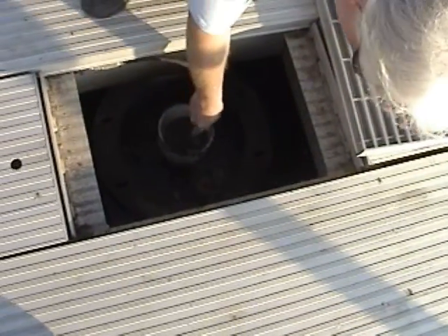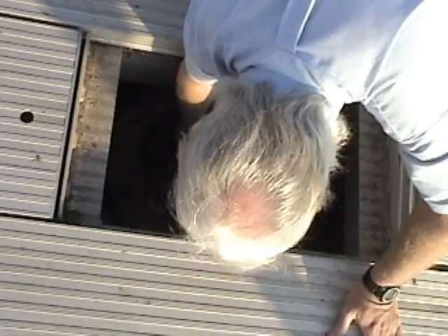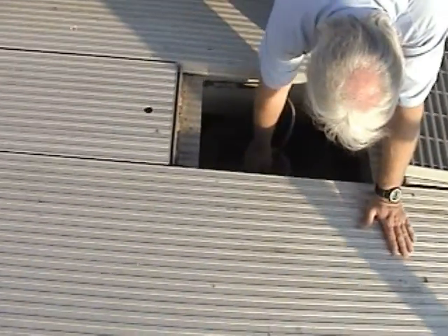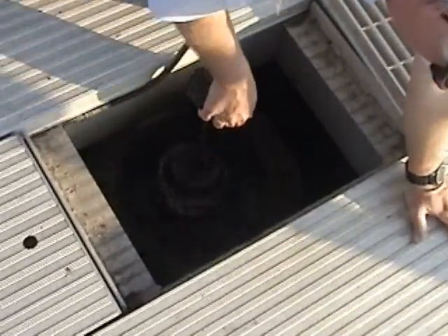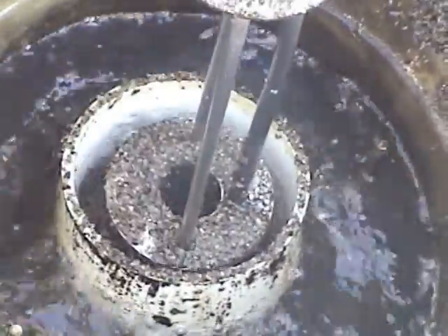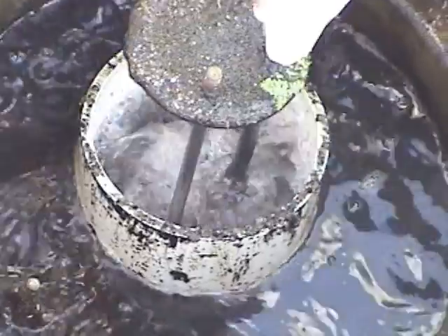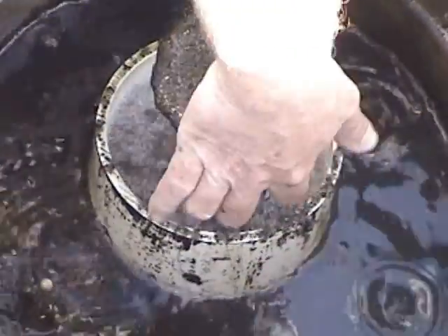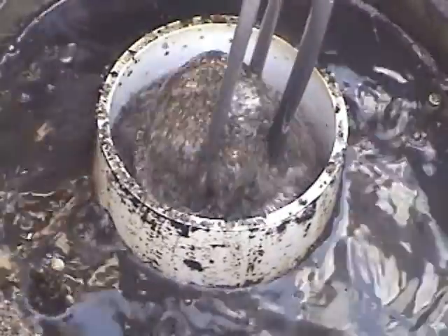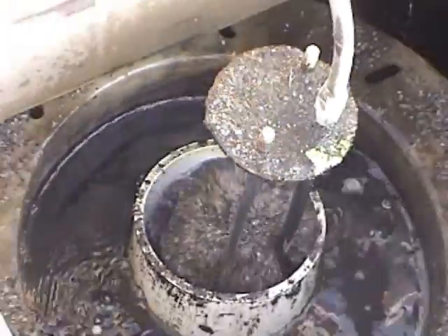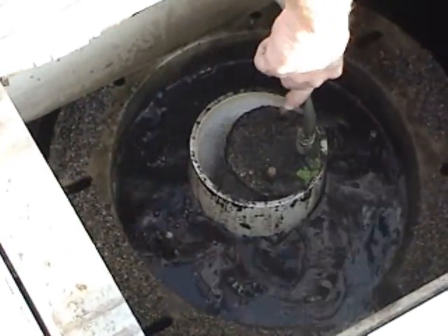If they have a lot of debris on top or something like that, that's probably that it needs to be looked at. But what'll happen? See, I'm going to bust it. I'll pull this one out, and see the sand's coming up. So that's the backwashing. The mucky, dirty sand is being cleaned. But see how it wants to fall all by itself. See that? I'm just dropping it, and then the sand is being pumped up the tube, so it wants to drop all by itself. So I'm just kind of helping it.